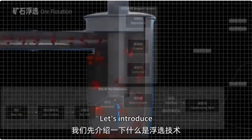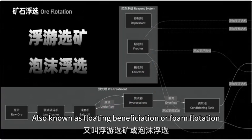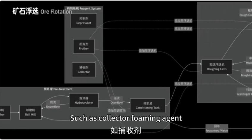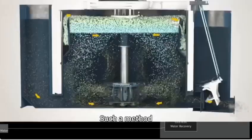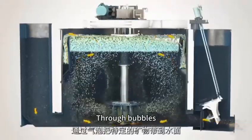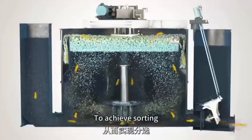Here it is. Let's introduce what flotation technology is. Flotation, also known as floating beneficiation or foam flotation. The principle is to use flotation agents, such as collectors and foaming agents, to alter the surface properties of the target mineral, separating useful minerals from unwanted minerals. A simple analogy is using bubbles as a foaming elevator. Through bubbles, bring specific minerals to the surface. The rest sinks to the bottom to achieve sorting.